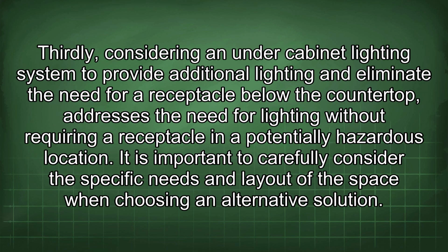Thirdly, considering an under-cabinet lighting system to provide additional lighting and eliminate the need for a receptacle below the countertop addresses the need for lighting without requiring a receptacle in a potentially hazardous location. It is important to carefully consider the specific needs and layout of the space when choosing an alternative solution.